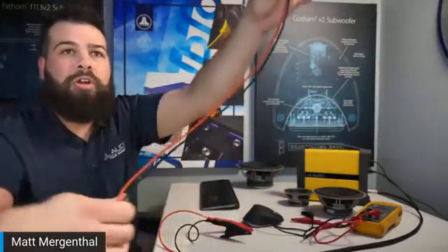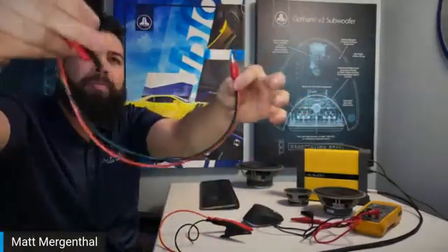So all it is is an RCA to banana clip, so we can put different ends on it. And this allows us to measure the voltage externally. So we're still measuring the current through the clamps, but the voltage will be measured through a separate input to Max. So that allows us to measure the voltage at the speaker terminal itself, which means there's going to be less voltage drop on this wire because there's less current flowing through it. Does that make sense? You get a cleaner, more accurate measurement because you're isolating things.